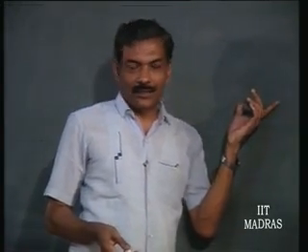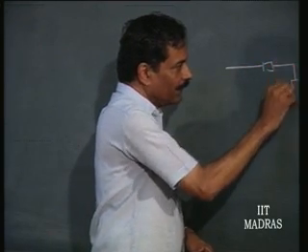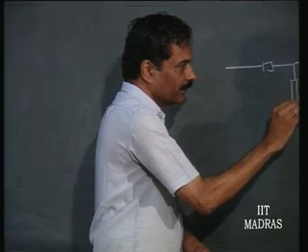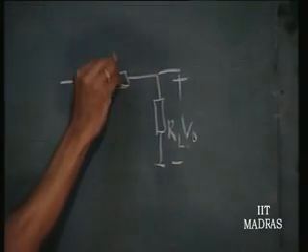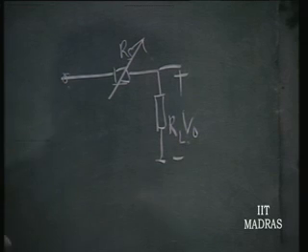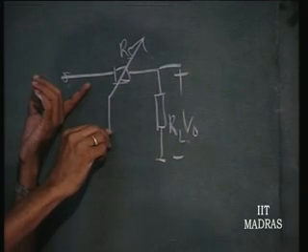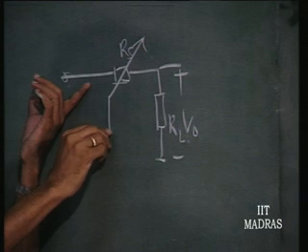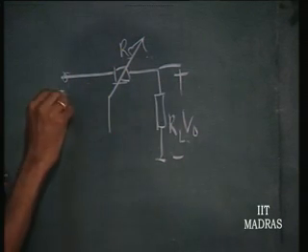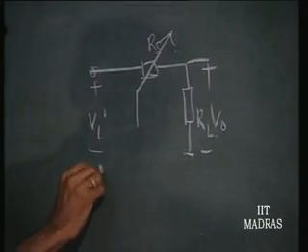Okay. The technique of maintaining output voltage across a load constant involved putting an active resistance, which is nothing but the transistor, and varying the drop across this, in the active region. Therefore, output voltage remained constant when input voltage was varying.